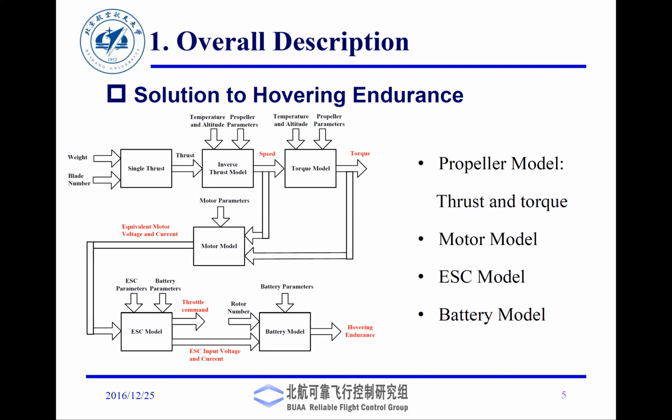Once we have specified all these, then we will find out how long that system can hover, how fast that system can travel, or what are the performance specs or flight parameters that we can achieve with that particular system. When I talk about these models, they are nothing but equations. Most of these equations are nonlinear, and many times you have to solve these equations simultaneously. So sometimes you have to look at tables, you have to look at some numerical solution, or you have to go back and forth, trial and error.